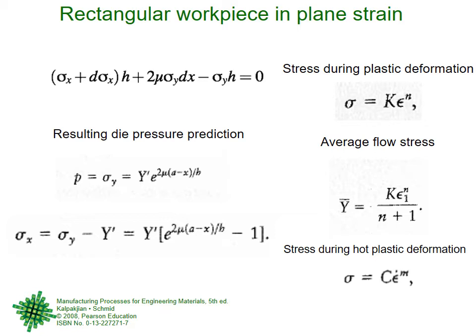So your applied stress is more than yield stress and less than ultimate stress. So here and in the remaining book, they will call it Y, right? It is not yield. This Y is just the stress in the plastic region, a stress in the plastic region that has been applied to deform the material into the shape of the die. This dash we will explain later, right?